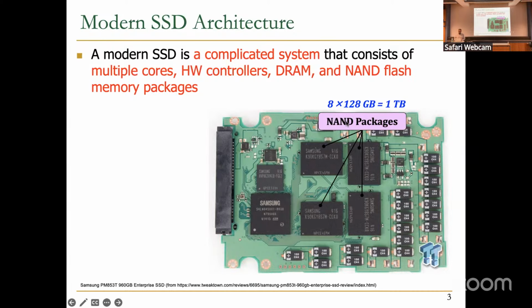And each package actually provides 128 gigabytes. So in total, this SSD provides 1 terabyte of space, for example. In addition to that, we have DRAM, which is LPDDR DRAM. The size of this DRAM is usually 0.1% of the total SSD capacity. And why is that? We're going to see later. But that's more or less the size of this DRAM.